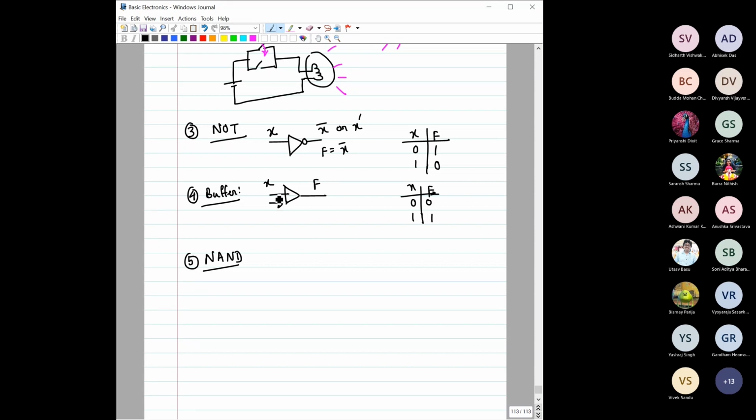Suppose you ask how many gates you can attach. I will take your question just after finishing this part. There is a current driving capability, which is also called the fan out. Different gates have limitations on fan out, so from that point of view many times we use a buffer. I will take this point after finishing these gates.